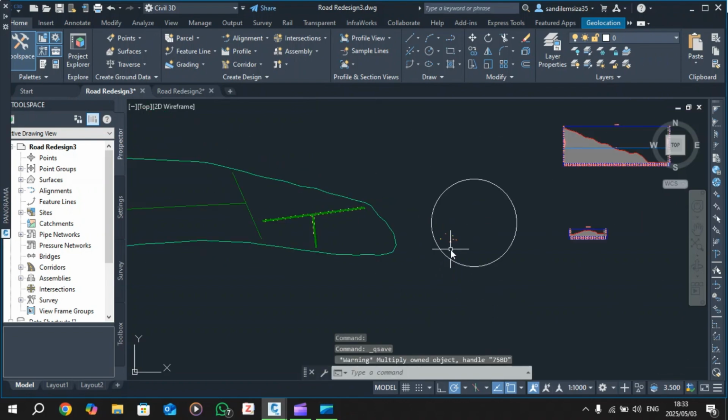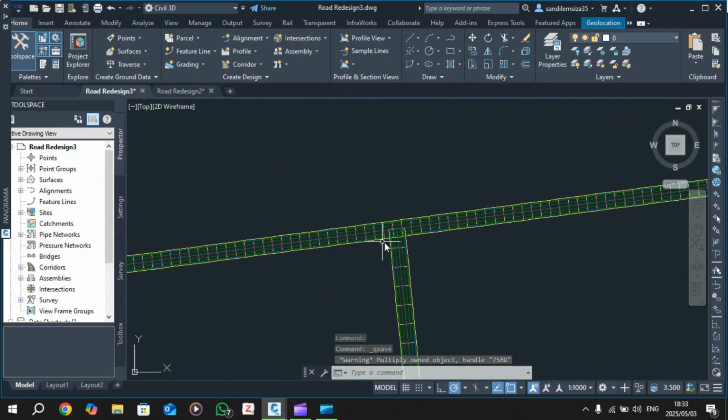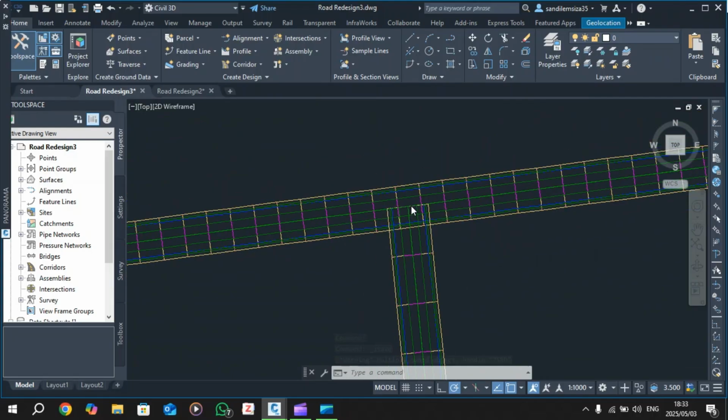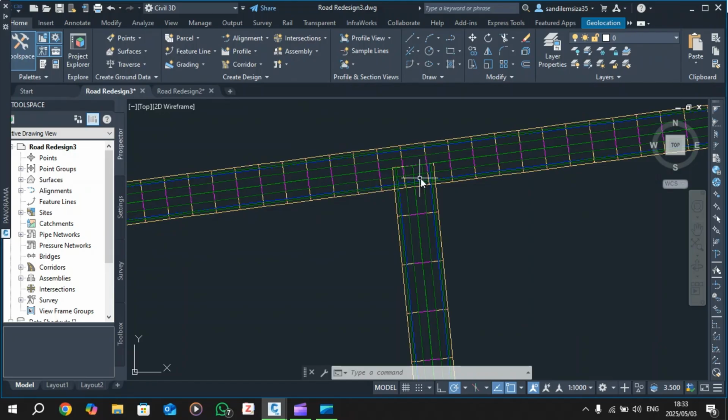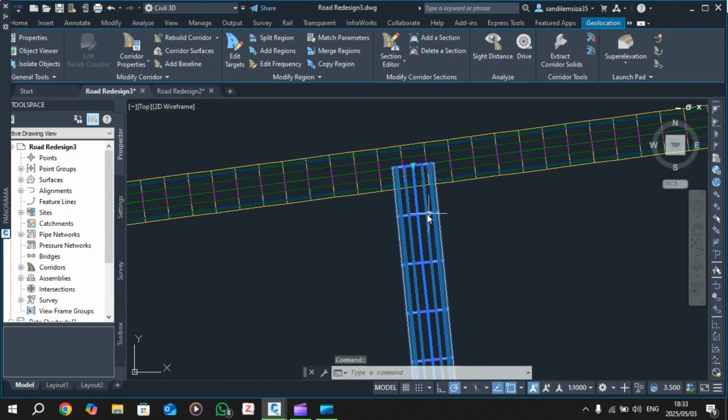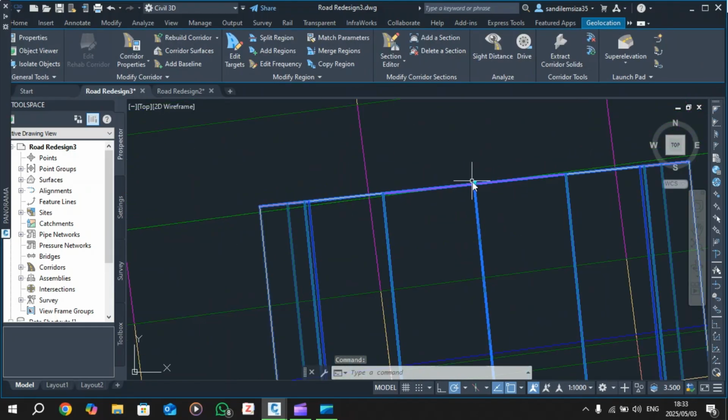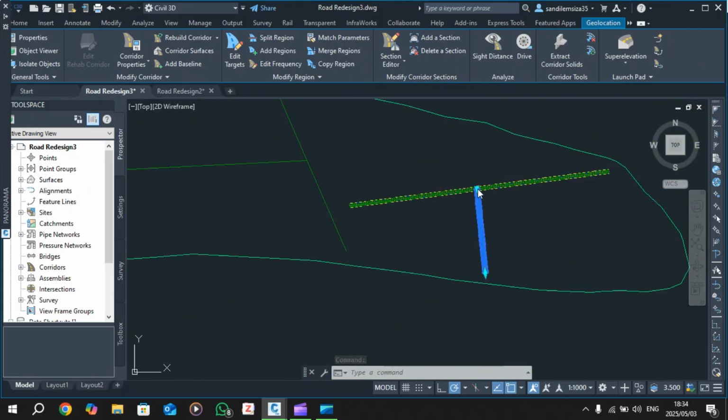Okay, we're on track. Now, let's prepare the space for our intersection. You need to have a bit of a gap here because with the automatic version, it's going to create its own dedicated corridor. So we need to leave out some space here. If we select this corridor, you will see that there's an arrow on either end of the corridors.